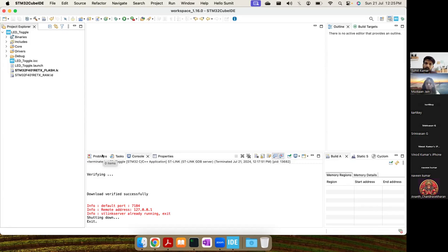And what do you mean by open drain? Open drain means PMOS is turned off. We need to actually program it when doing bare metal programming. So PMOS is turned off, only NMOS is active. According to the signal which we give, there's this NOT gate which we connect, and then we give an input. Accordingly, the pin will turn on and off.